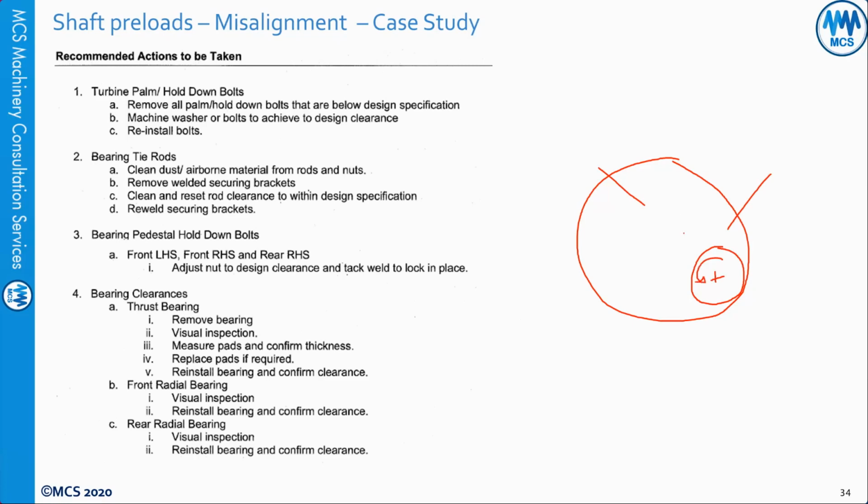How do the proximity probes work? They work with the voltage gap, and the change in the voltage gap is translated to vibration. But if the shaft is squeezed here, it cannot move, and it is preloaded to stop in this direction because of high preload, because of misalignment, because something restricts its motion. So the shaft has lots of energy inside it, and because it's near the bearing cap, this energy transfers to the bearing cap, causing high vibration. You can feel it on the bearing cap.